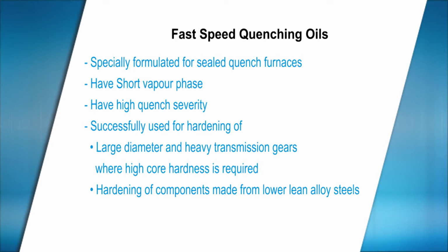By virtue of the short vapor phase and high quenching speeds exhibited by fast-speed oils, these products are extensively used for cold quenching applications, mostly in furnaces where controlled atmosphere is maintained in order to achieve stable performance over a long period.